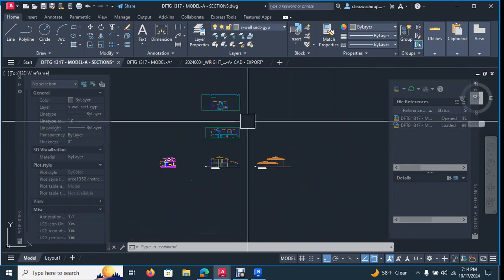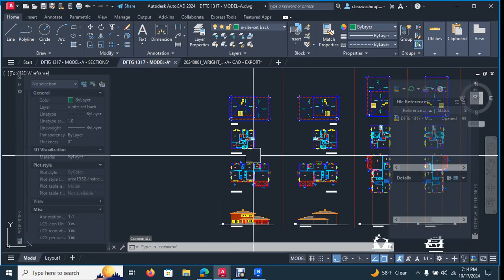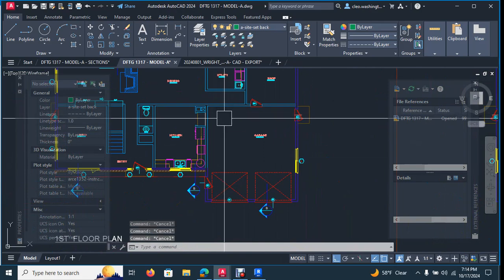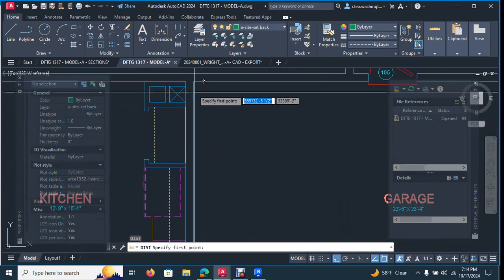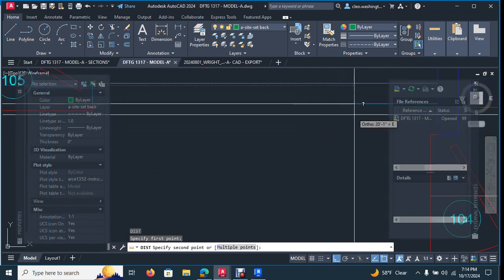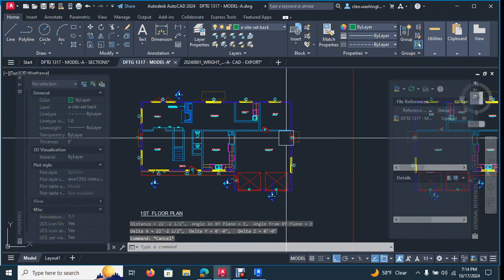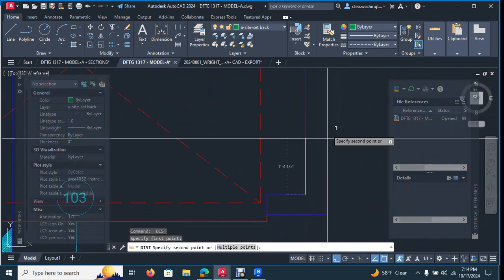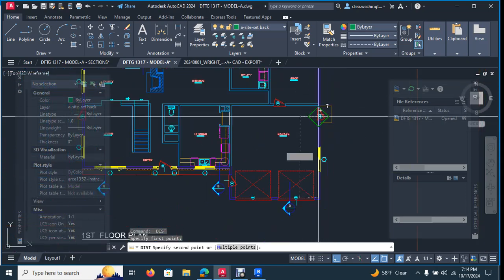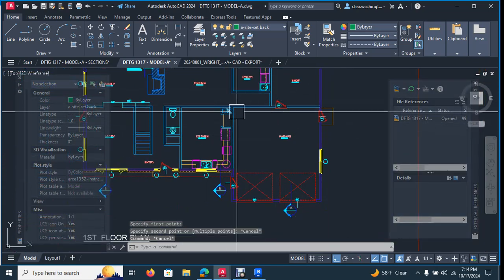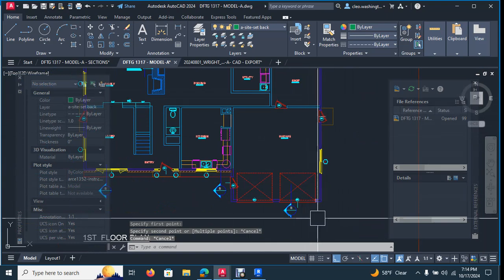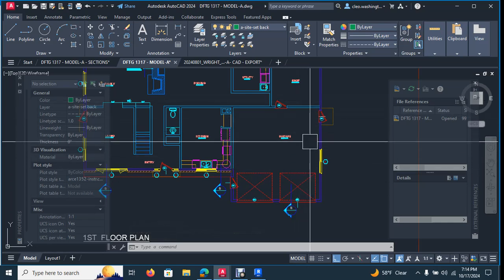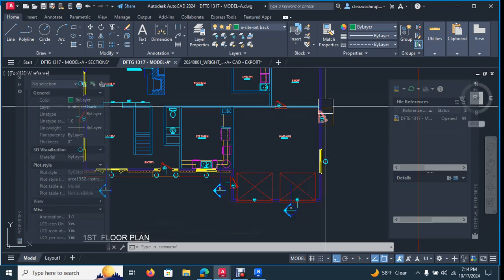Yeah. Let's go back and look here, okay. So what's the shortest distance? I'm just gathering some information, guys. What's happening is the rafters in the ceiling at the garage will always span the shortest distance. So I think the shortest distance is going from here. I think this is longer. So we'll have beams 16 inches on center going across here.